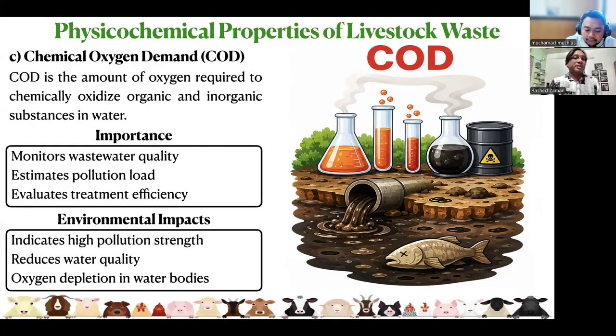It estimates pollution load by showing the amount of oxidizable waste materials present in the wastewater, and it can also be used to evaluate treatment efficiency, because by determining the COD value before and after treatment,